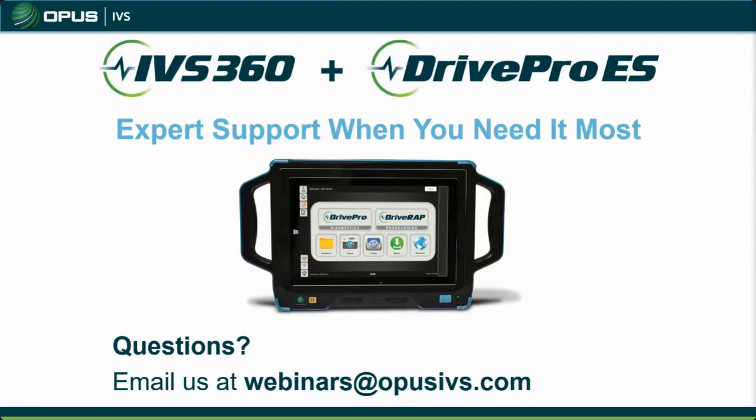Andrew, I know you come in the morning, and that is open on your desktop, ready to go. It is ready. I keep that open all the time, and I try to add to it too. I often will ask the guys that I talk to on the phone, hey, if you got a manometer and you're measuring this stuff, let me know what you find, before you replace the valve and after, and you'll see on there what the readings are for some of these aftermarket valves, and they are just all over the place. Totally not consistent with factory valves. The data kind of bears out the fact that these aftermarket ones are just often no good.